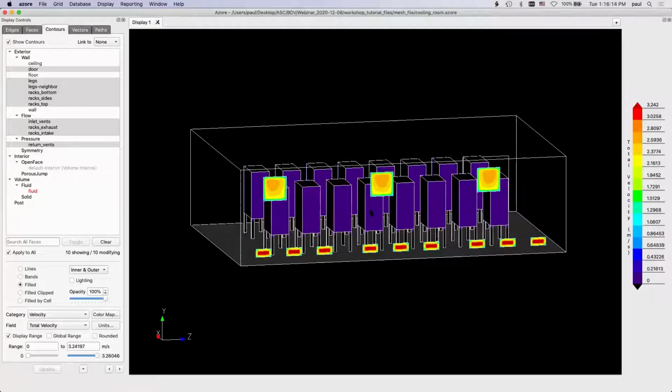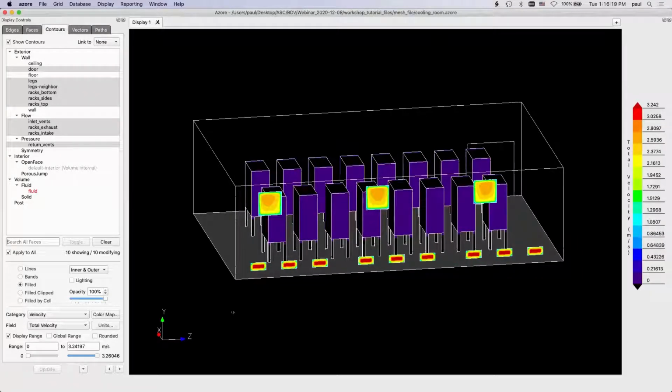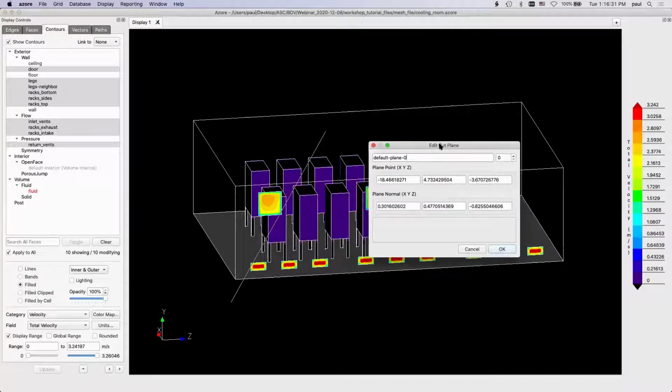on those cutting planes. And in order to do that, you hold down the shift key and you drag with the right mouse button. As you do that, holding down shift, dragging with the right mouse button, it'll give you a line where you're going to cut. And then it brings up a window to give you the details of that. Well, where I just cut is not really where I want to look, so I'm just going to cancel that.